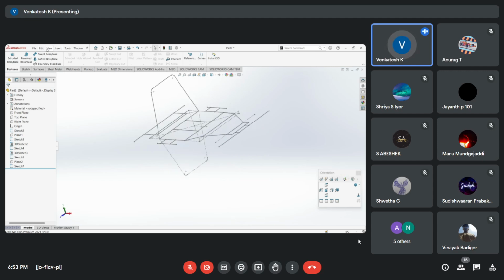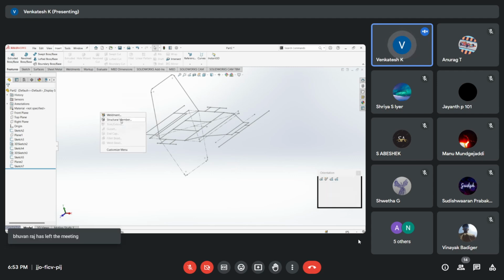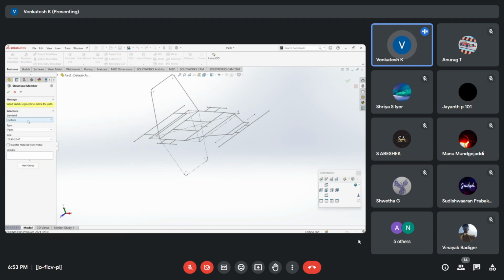There is an option in SolidWorks itself which gives you the pipes option at once. Under Insert, there are Weldments. In Weldments, there are Structural Members. These structural members are pipes. There are multiple types. Currently, there's only pipes, not custom. If I go to ANSI, yeah, these are pipes. Different pipes. There are I sections. This is an S section. I'll show you what an S section is.